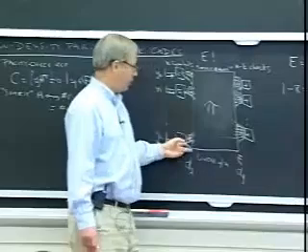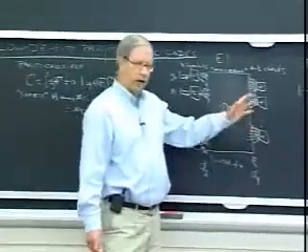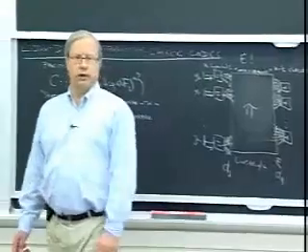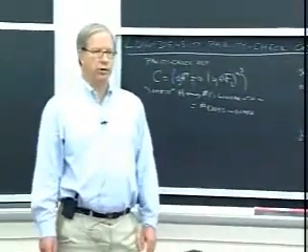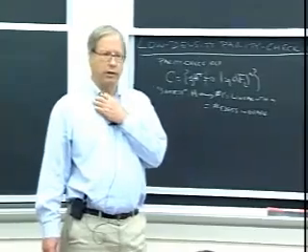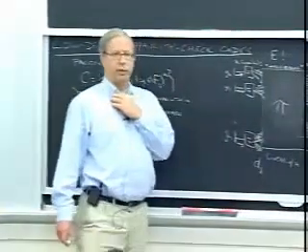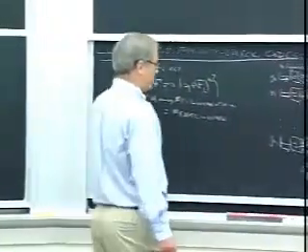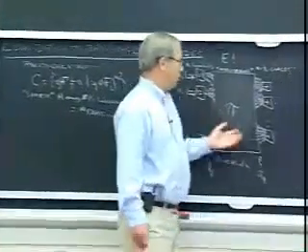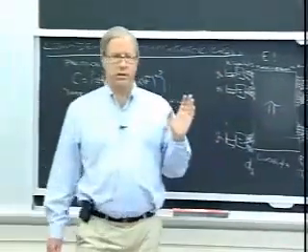Basically, everything that's over here then has to be a code word. So whenever all the checks check, just based on hard decisions, you stop. So if there's very little noise to start with, this can happen very quickly and terminate the calculation well short. Or you have some maximum number of iterations you're going to allow yourself. If you go 200 iterations and these things still don't check, probably you would say, I've detected a decoding error.